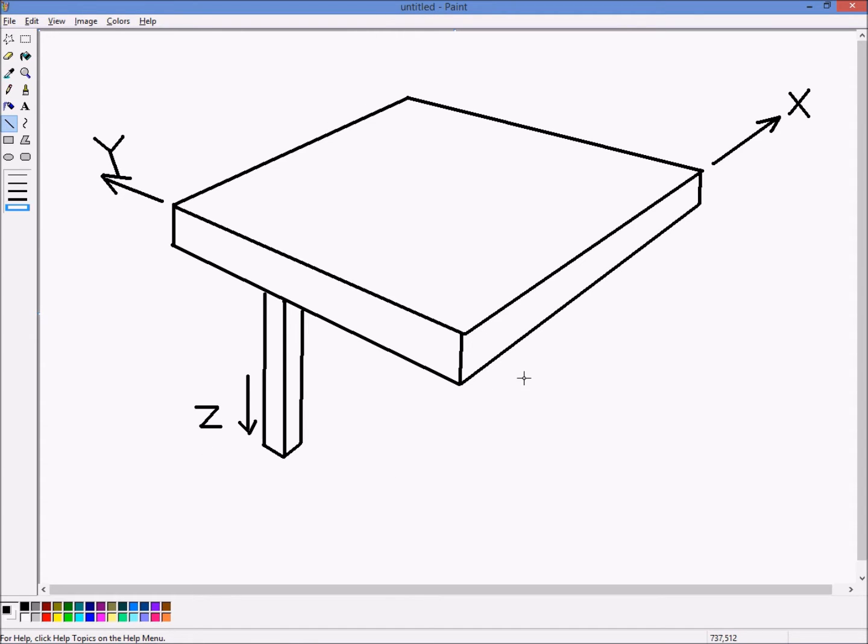So in order to safely home the machine, we have to move first the z-axis up and out of the way, which is in the negative direction. And once the z-axis is out of the way, we then have the freedom to send both the y and the x to their home sensors concurrently.